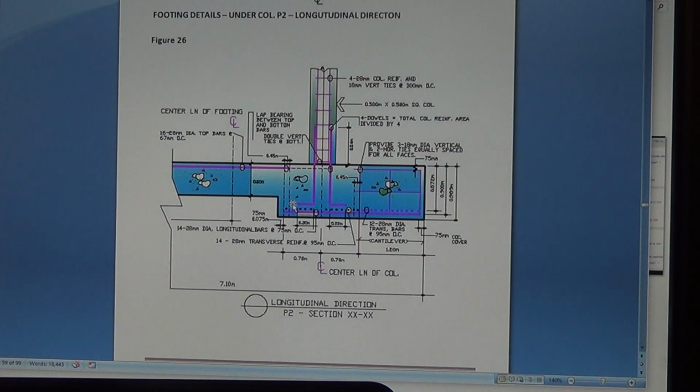Okay, in architecture, the cut bars, the top, the cut there, and the bottom bar. And for civil engineering, I don't cut it, and I have to incline. I have to continue the top bar there going down here at a 45-degree angle, same as the picture in the first video about foundation design that I was talking about.